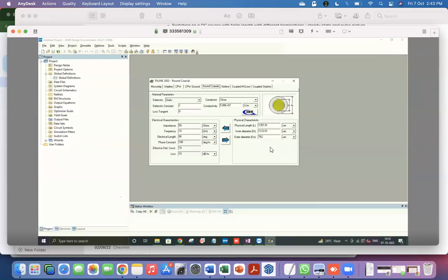Okay. So we then very quickly looked at the strip line, the microstrip line, and also the CPW. So we'll spend a little bit more time looking at those things again. Strip line here is basically a center conductor which is buried inside a dielectric, and there are two ground planes on either side.